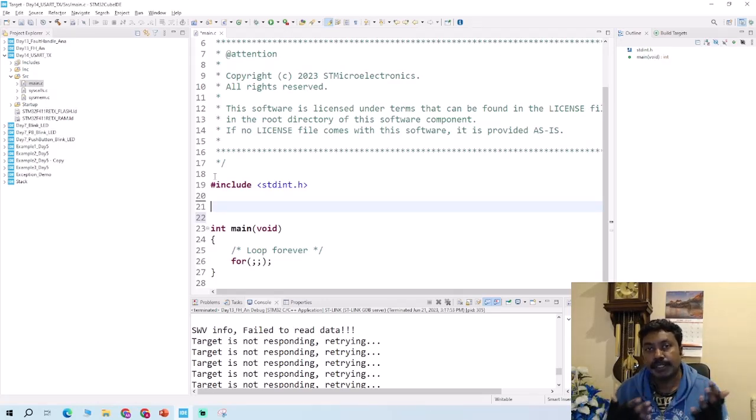Okay, first we learned about how we need all the bus information and the peripheral information. When we talk about bus and peripheral information, everything is controlled by registers, and those registers are programmed at the address of that particular register. So in embedded C programming, those addresses are a must. You need to go into details of every special function register and look for that address, copy it and bring it here because you're going to use it, and I'm going to show you how.